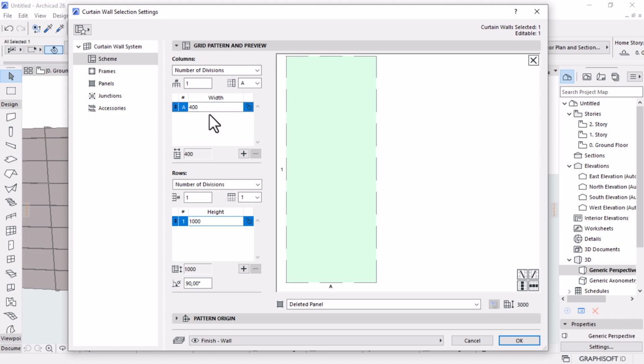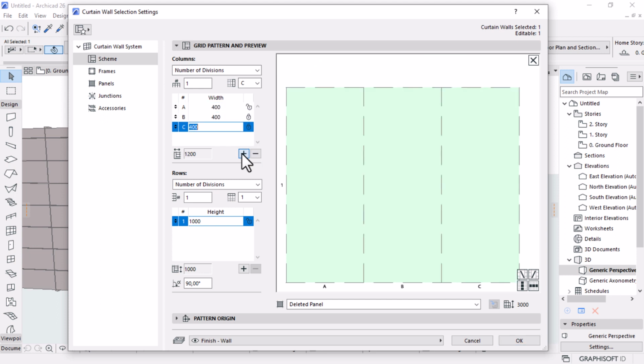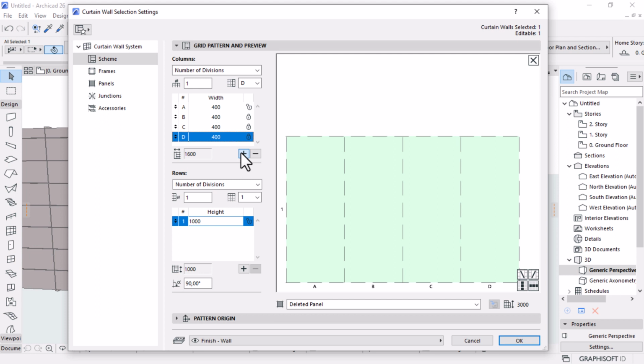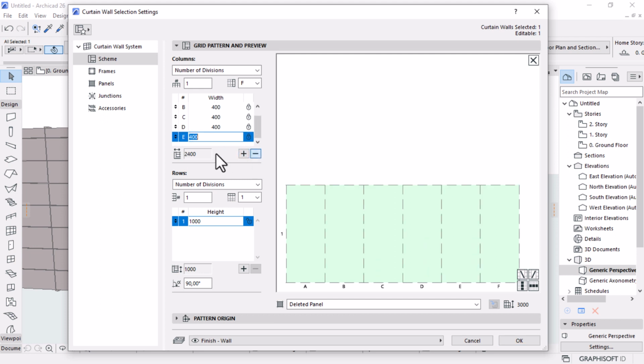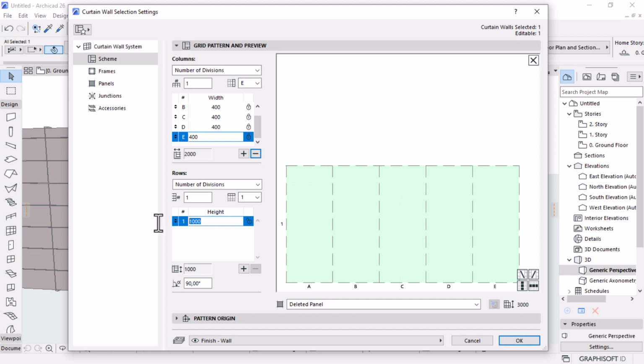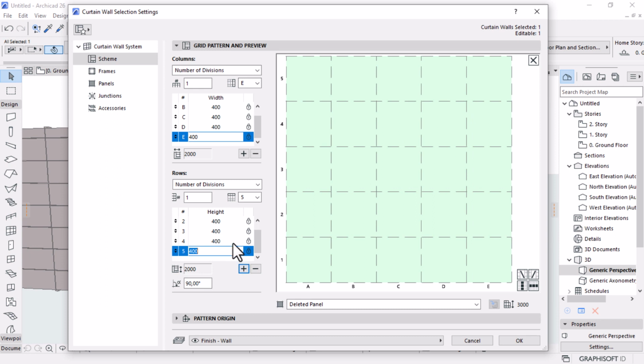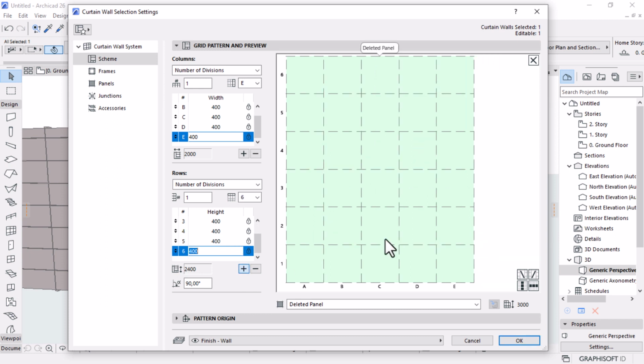It's better to start by naming, or defining, the height of that particular column or row, and then if you multiply or increase the number, it will repeat the value, which is 400. So I need to have this 6. Yes, I'm going to have 6 of this. And then for the rows, I'm going to make them 400 high, and then I will make 6 of them as well. Okay, that's basically the foundation, or the basic pattern, to achieve that.